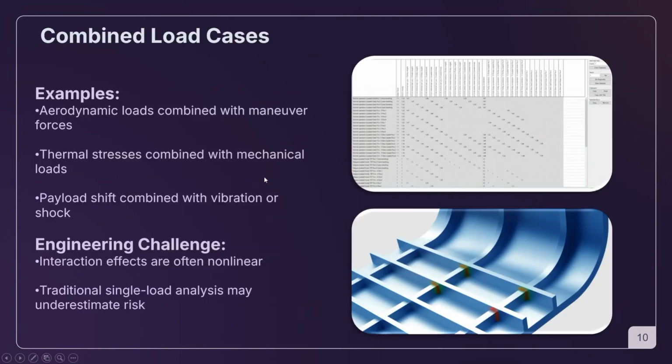Another thing is that often these different cases should be taken with different safety factors, which may result in hundreds, even thousands of different load combinations, taking into account different purposes of the equipment. So this is for sure the challenge of the engineer, how to combine all these effects in one analysis and get one solid answer whether the calculation was right. And for sure, single load analysis may underestimate the risk. So the only way to comply should be to combine all these extreme cases together.